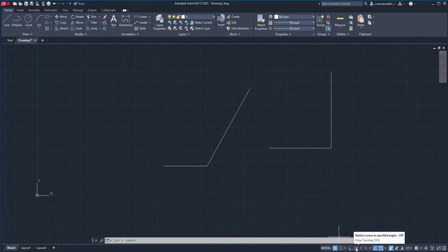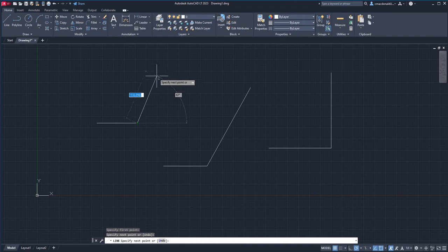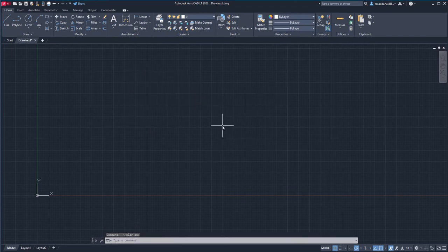We left click, and now it's back on again, just like that. Now, a fairly easy command that's based on the status bar here is Ortho Mode. I'll show you how this one works, and it's quite simple. You'd simply left click, and it automatically shifts away from polar tracking. You left click Ortho Mode, and watch what happens when I try to draw a line.